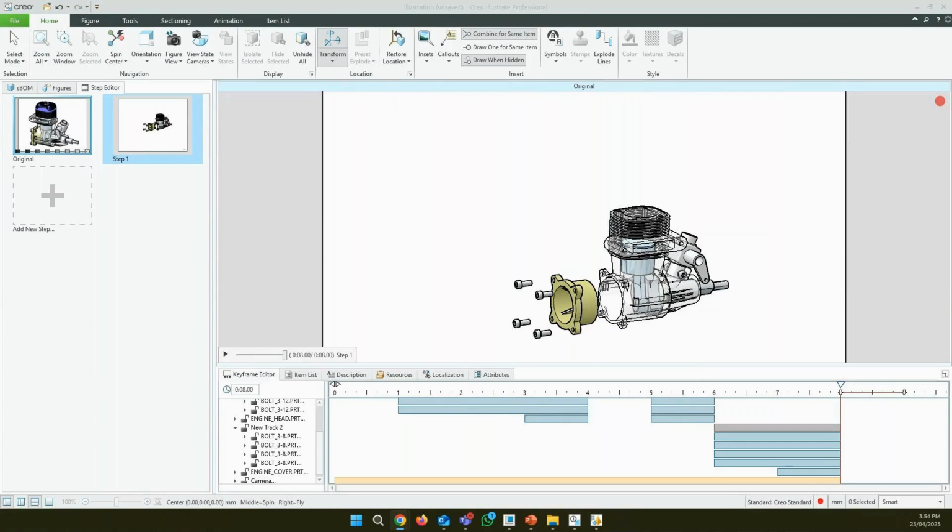The question is, after Explode view, can we save as a CGM format? So the answer is yes, you can export it as a CGM format. However, if you are creating an explode line and then exporting it as a CGM file, then you will have to use the 2D illustration view to export them. But yes, you can export after exploding. You can export them as CGM format.